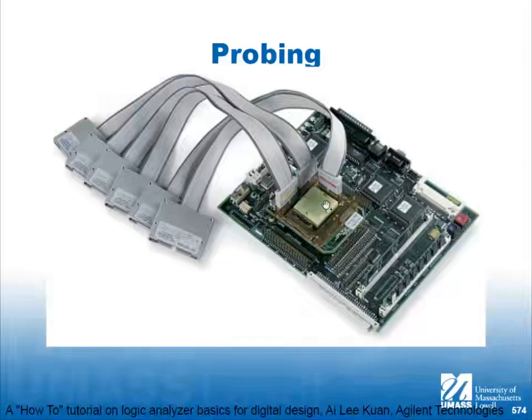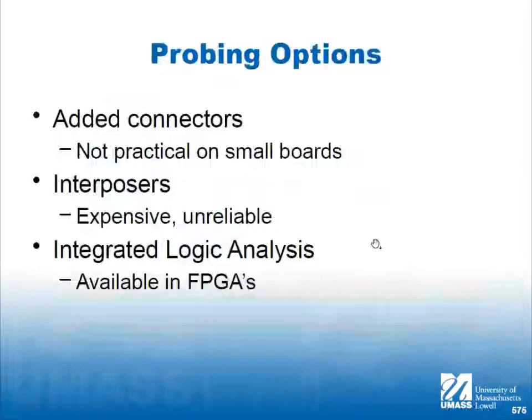And connectors that are this dense have connection problems anyway. If you have 2,000 pins and you make the connector a bunch of times, you start to see intermittent connections. Remember I said all those problems with probing, and I amplified all the problems with probing. Now I'm going to remove probing completely.